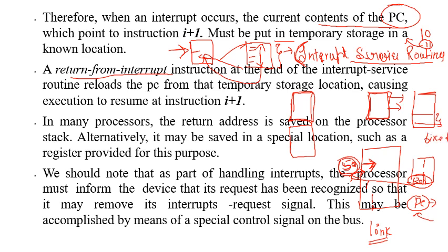The address locations that store the interrupt service routine are fixed, whereas a subroutine starts immediately next to the main program. When the main program ends, the subroutine program starts. Or subroutines can be written anywhere in the program, and they have to be referenced using a label whenever required, or called using the address whenever required.